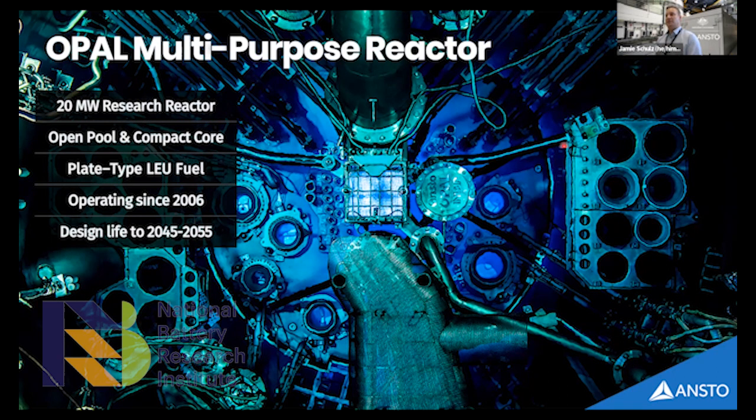So looking at the reactor here, you have what we call the core in the middle, which has 16 fuel elements. This is the main cooling pipe, which brings cooling water into the reactor. We have what we call the reflector vessel, which is this structure around the outside. Within the reflector vessel, we have heavy water, and within that vessel, neutron fluxes build up. Within that, we have penetrations down inside the vessel, which allow us to do irradiation. So we have locations here for silicon, for the transmutation of silicon.